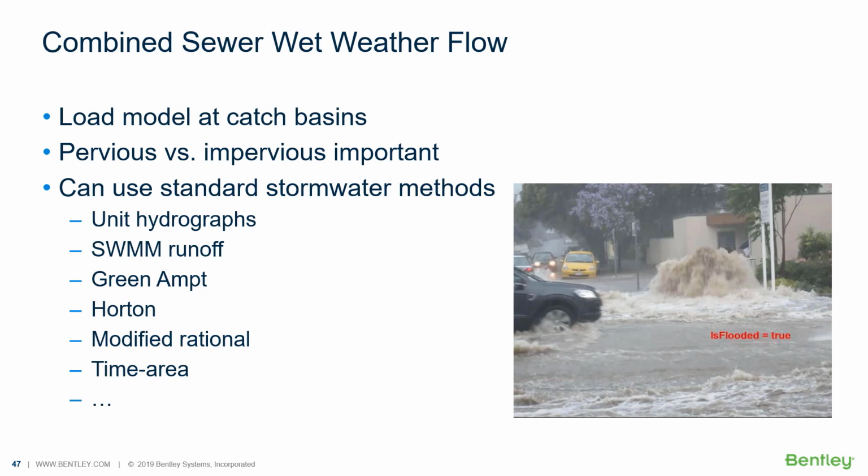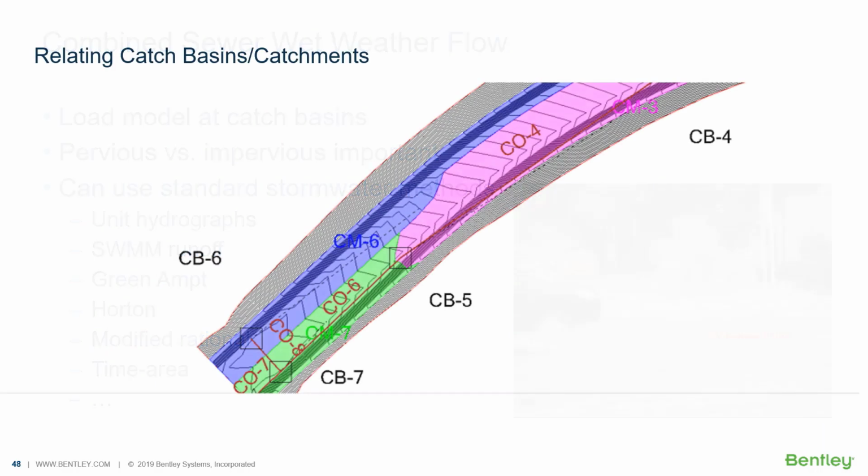So these models, even though they're very theoretically soundly based, still are hard to calibrate because there's so much that goes on. You're not going to be doing every little low spot in people's backyards and such to account for storage. So it's going to be tough to get it really precise. But there are methods here that are rationally based, which is really good. So you have some advantage in doing stormwater modeling.